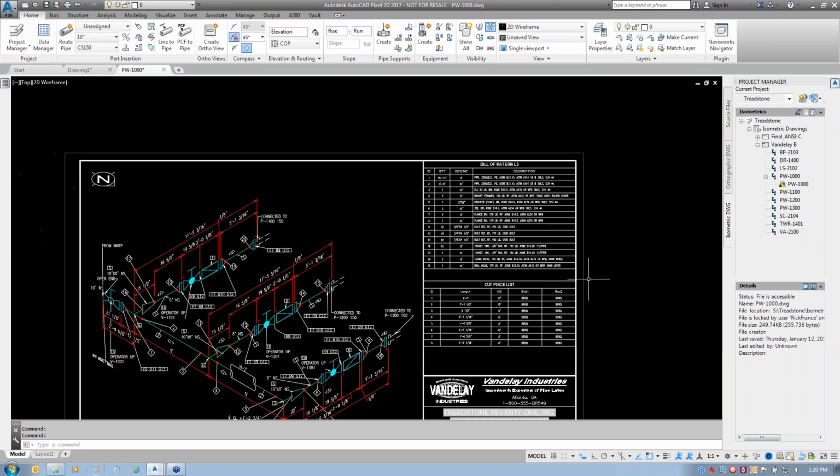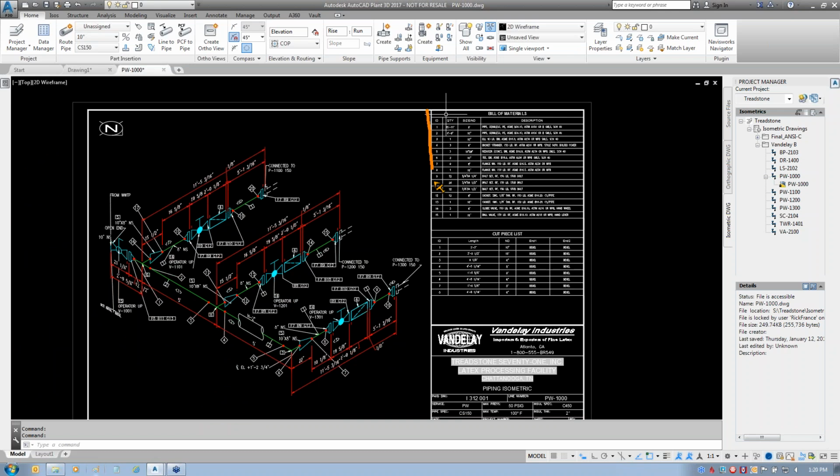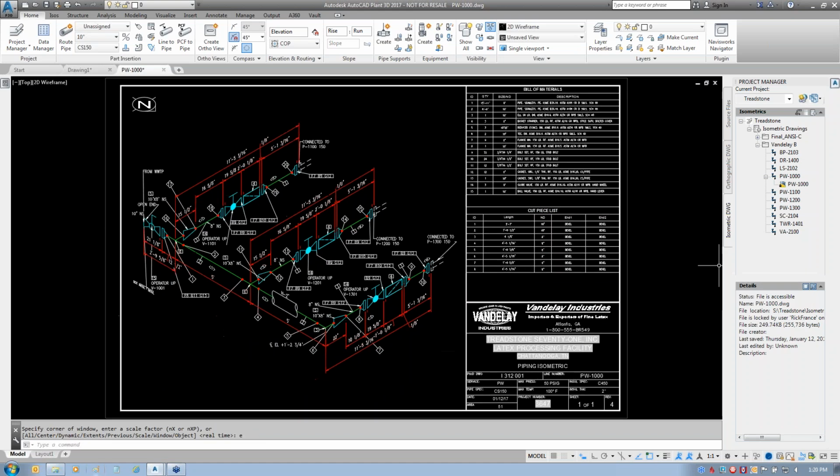I could also do some things to where my draw area, for instance, on my bill of material maybe was here, do a cut list working up that went halfway, and then a weld list working up halfway. Problem is that weld list would cause additional drawings just because there's so many welds. So it depends on what information you want here. If you're going to be using a weld list, I suggest a D-size drawing to get everything in there, which may affect what text fonts you use, because you definitely want to use 1/8-inch text on D size, because you're still going to probably plot it at a B size, and so you probably want to use 1/8-inch text.